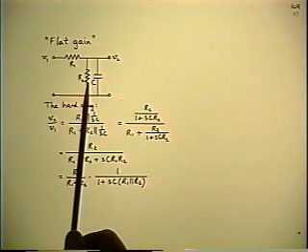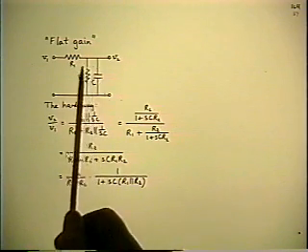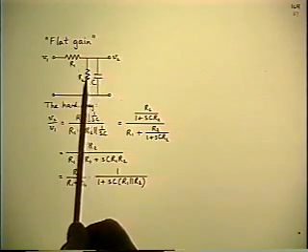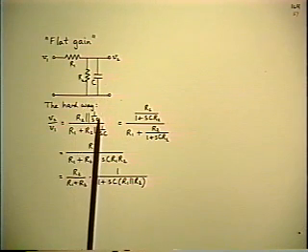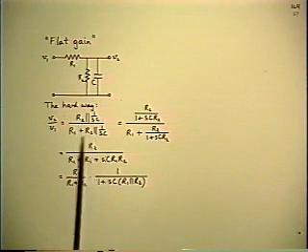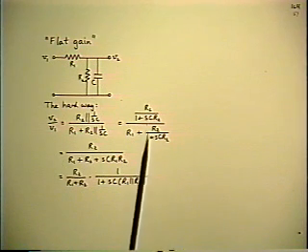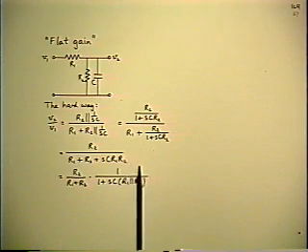So you can treat this as a voltage divider. And the formula is you take the bottom branch of the divider, which is the parallel R2 and C, and you divide it by the sum of the 2 branches, R1 plus the other stuff. And then you start grinding algebra.